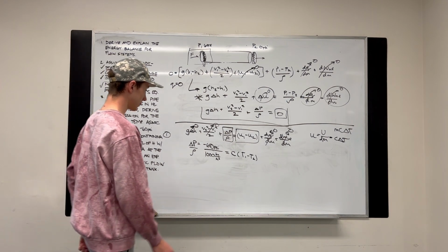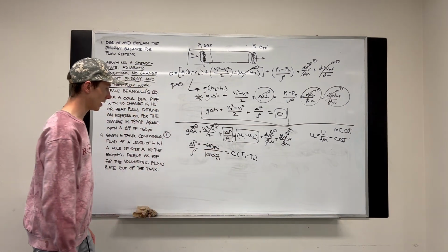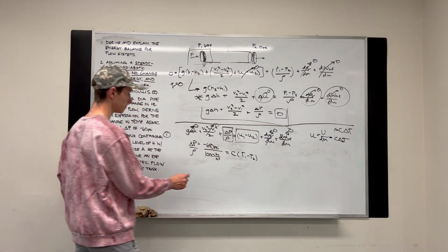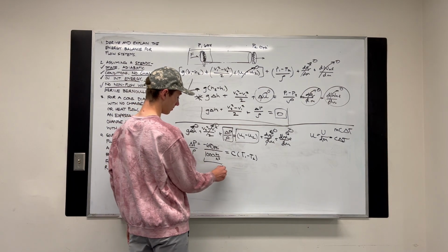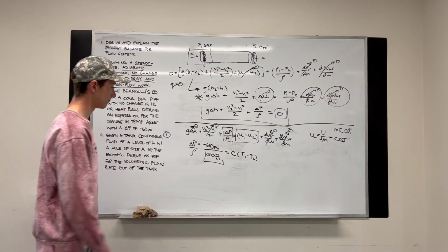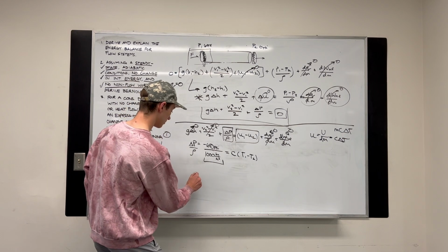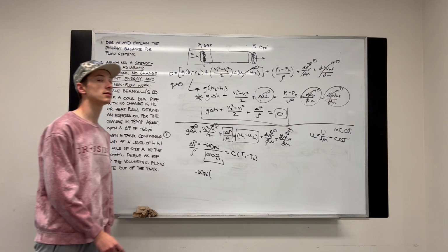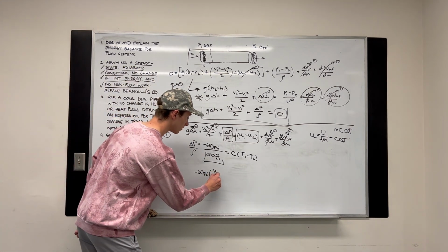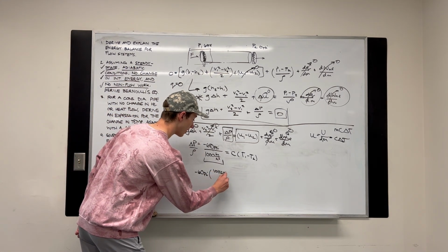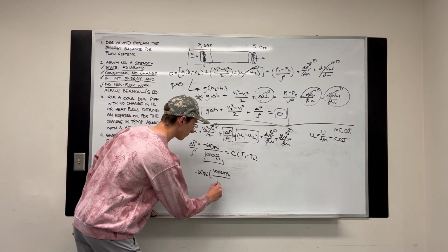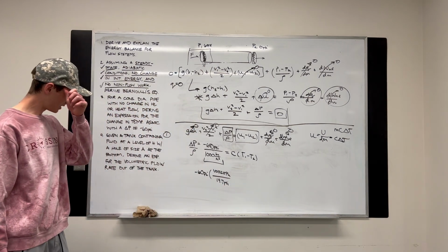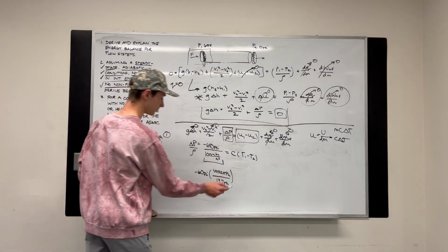Let's go ahead and get our pressure in better units. We have pounds per square inch here. We're gonna put that into pascals, so that we can make it work with our density. We have negative 60 psi times, there is, oh boy, 101.325 pascals per 14.7 psi. Does that sound right? I'll check that later.